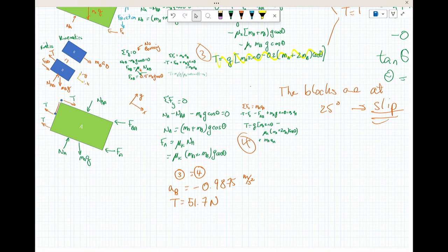If you have considered all of the forces, a single force that is in the wrong direction will not affect your calculation. It will correct itself. However, if you have multiple forces in the wrong direction, often it causes more confusion and things get messy. So it's not a perfect system, but it's not a bad system.